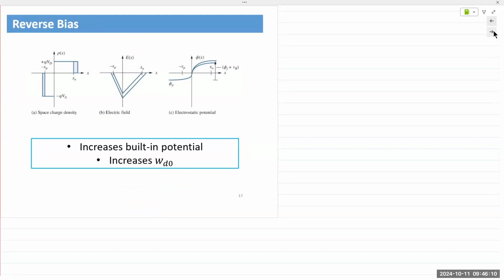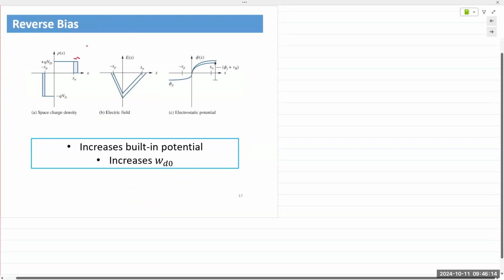So the reverse bias, we talked about how the depletion region width increases. So if it increases, it's increasing physically. And because it's doing that, the electric field also increases on both sides of the junction, which results in an increase in the barrier potential right there, VR.